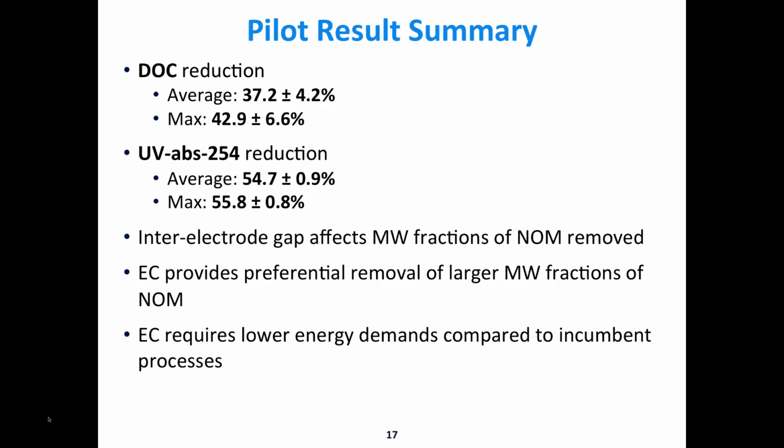This was actually very challenging water to work with respect to electrocoagulation and chemical coagulation, because it had a very low initial specific UV absorbance, or SUVA, value. Initially it was about 2.2, and we were able to reduce the SUVA to about 1.71, where there has been a published stopping point of 1.75, based on the NOM and the molecular weight fractions of NOM.